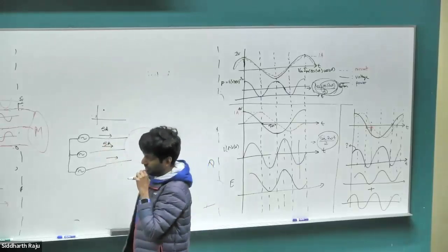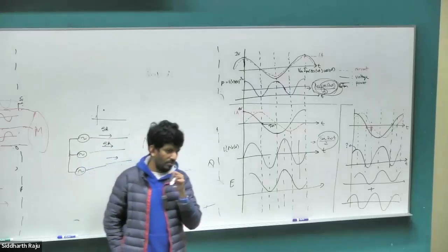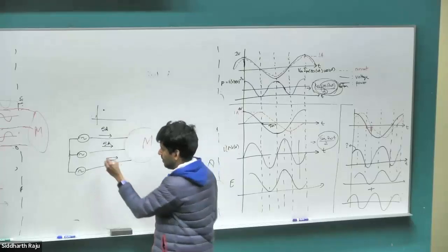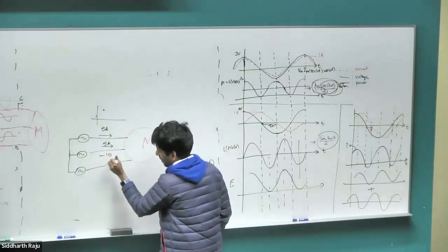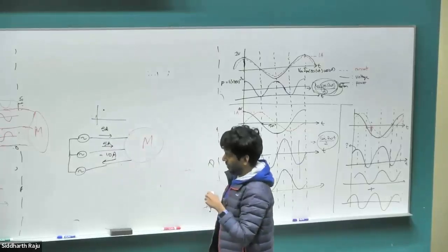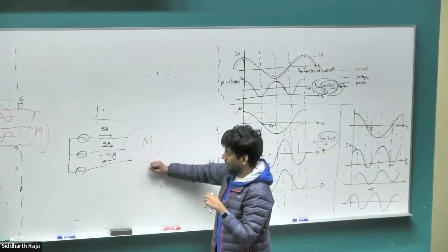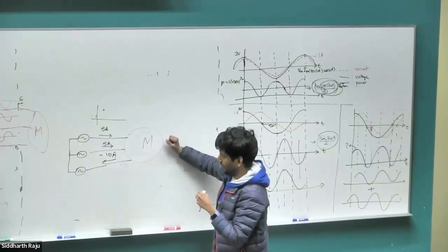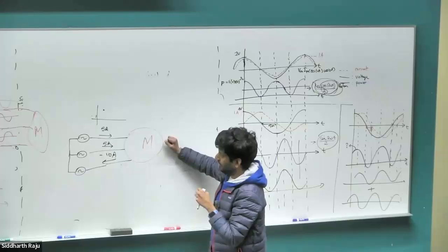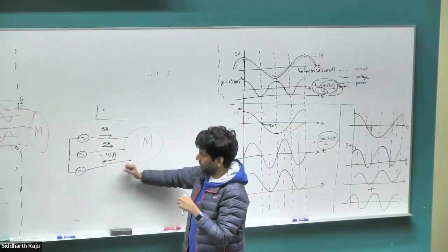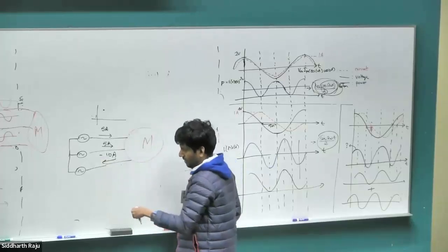What is the current in the C phase going to be? 10 ampere. Is it 10? Negative 10. Or 10 ampere in the other direction. Right? We don't need an external additional wire to close this network. As long as, again, this is balanced. Even if it's unbalanced, you don't need an additional wire. The voltage will become poor if you don't have that additional neutral wire. But the idea is we can have 3 wires and get the power into the system without any issues.